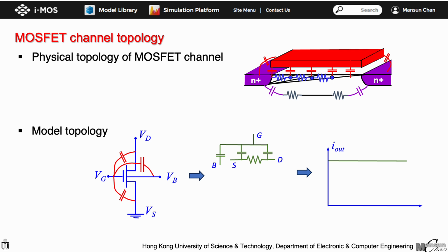We can implement the distributed network topology of a MOSFET channel by adding internal nodes. It improves the accuracy of the frequency response, but may lead to significant delay in the simulation time due to the increase in size of the Jacobian matrix. It may be acceptable in frequency domain simulations as no iteration is needed. However, the delay added to transient and DC simulation is usually not acceptable.